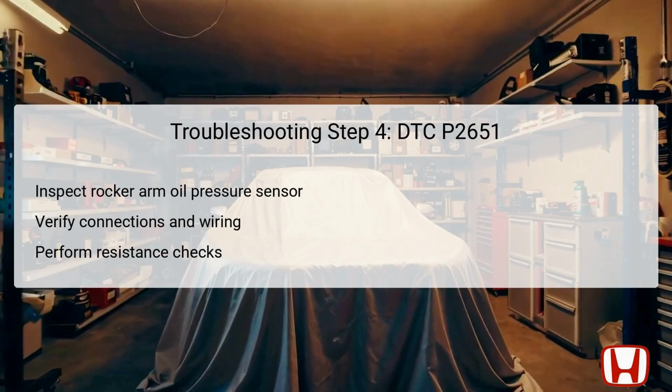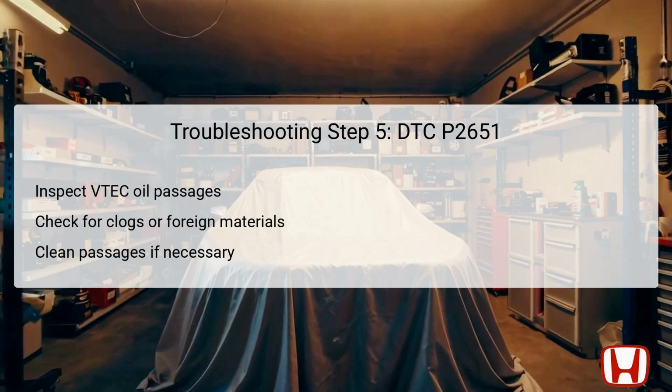Additionally, perform resistance checks on the sensor, as a malfunctioning sensor may exhibit readings outside of the specified range. If the sensor's performance is not within the expected limits, it may need replacement. Documenting your findings during this step will provide important insight into whether the sensor is the root cause of the problem.